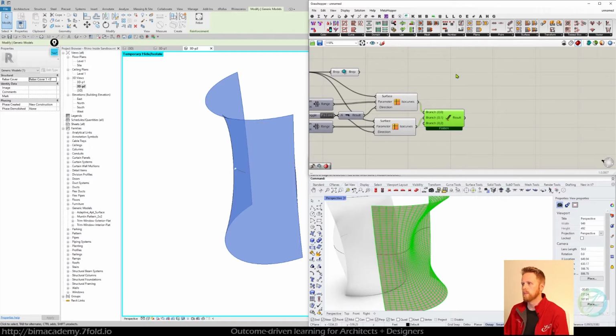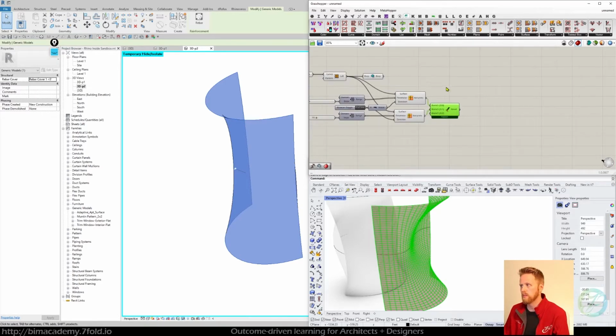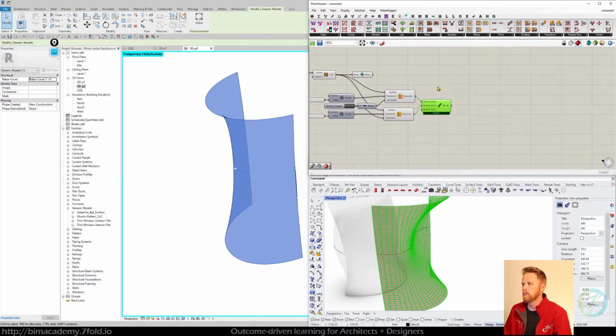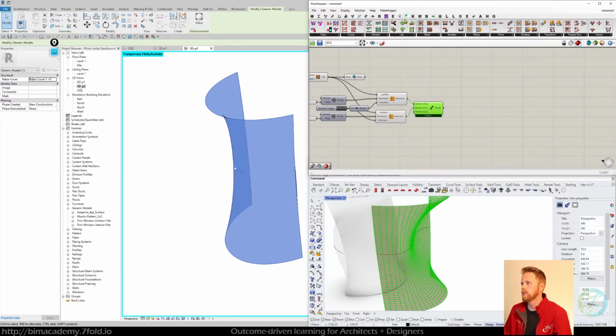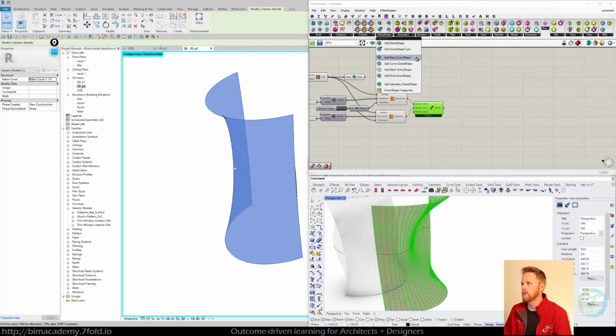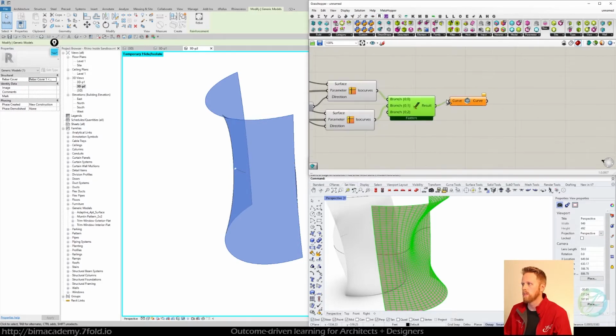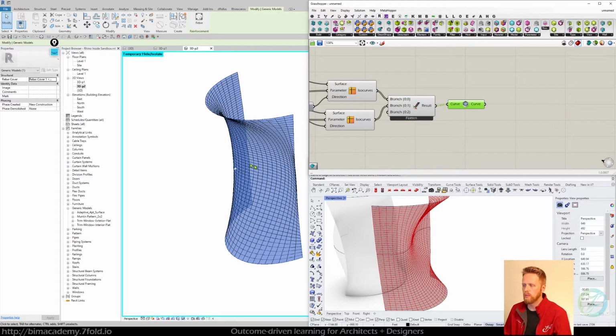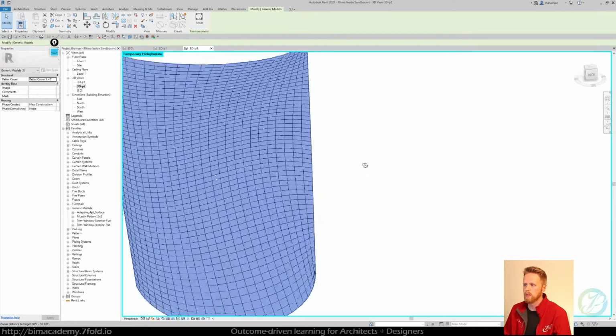And the way that Revit is rendering all this geometry, it's not going to matter. You just have to know that it's serializing some information through the script. So if you stop using the script, it all becomes an individual element unless you do some additional steps to group it before you do so. But right now, you could basically just go up to Revit, and again, direct shape, and just do an add curve direct shape. And now that's going to go from Rhino over to Revit.